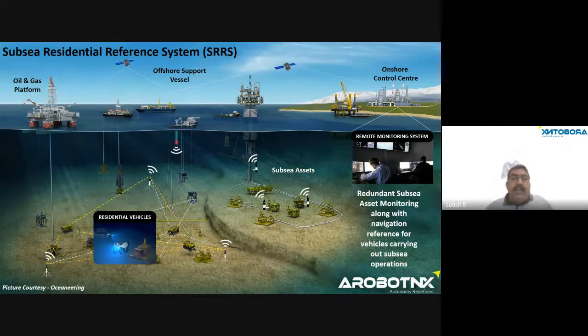In broader terms, Sparse LBL is a game changer, and it is definitely going to bring a lot of advantages. It introduces the INS and the SLAM calibration, where the SLAM calibration has 2D and 3D calibrations, and just three transponders with a powerful INS can be enough to carry out any kind of subsea operation.